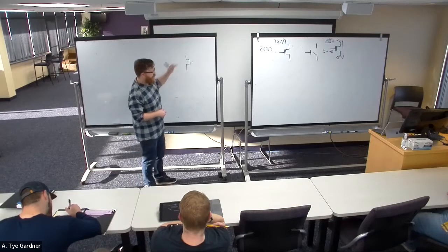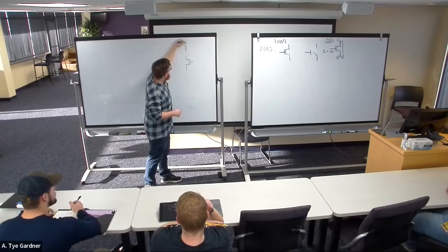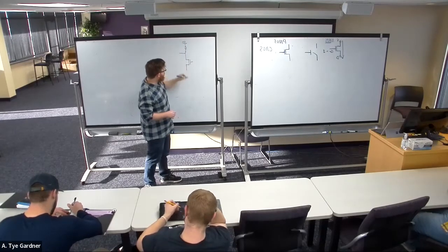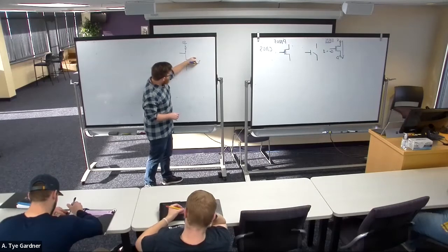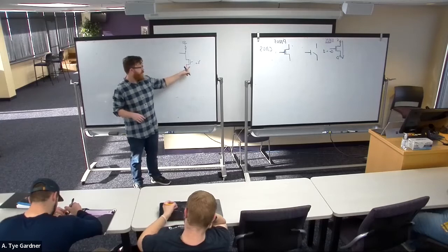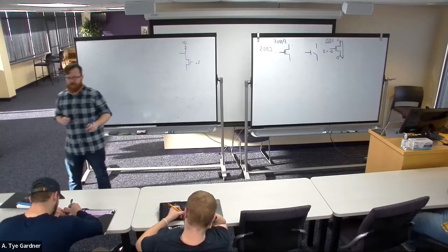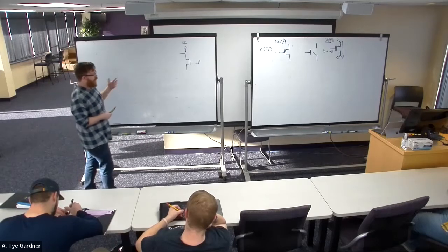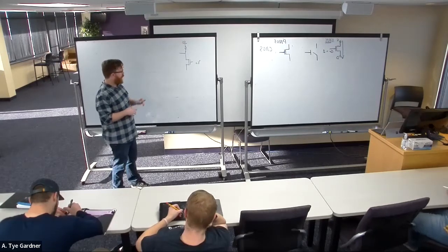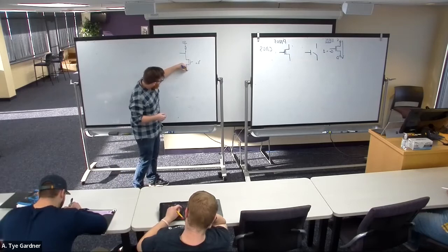All right, well, we know this is a switch. I can put a resistor up to VCC, take the output. If I put in an input voltage or some digital signal, say this is a 5-volt CMOS, that's allowed. They can have 5-volt CMOS devices. It could also be a 1.8 or a 0.7 volt, or it could be smaller. But then we put ground here.